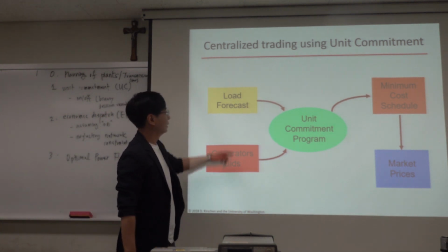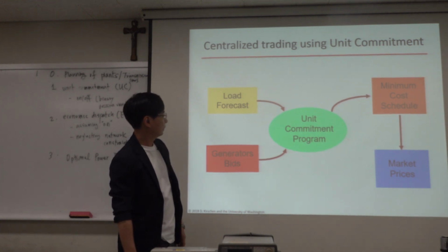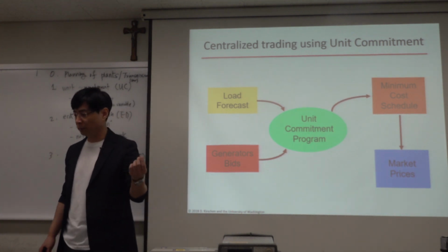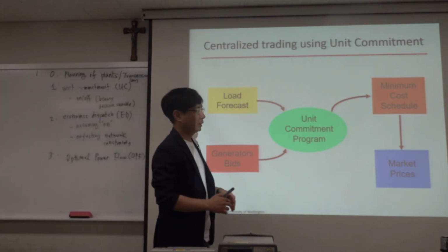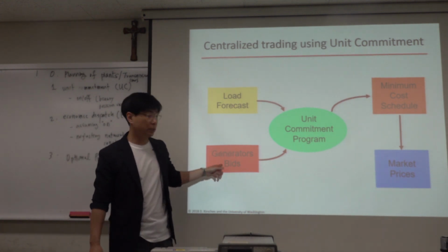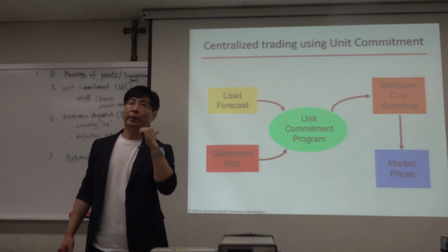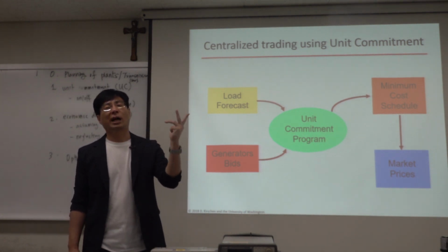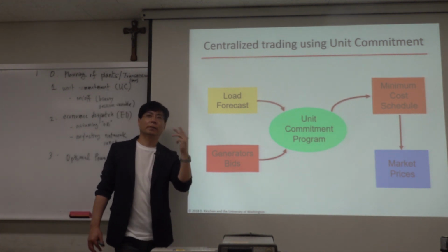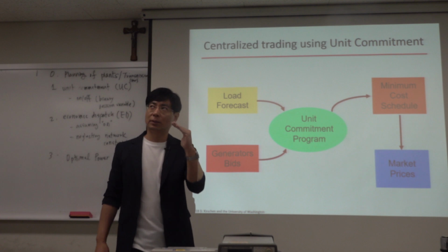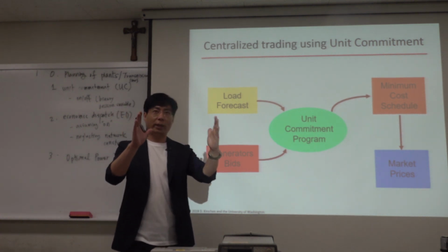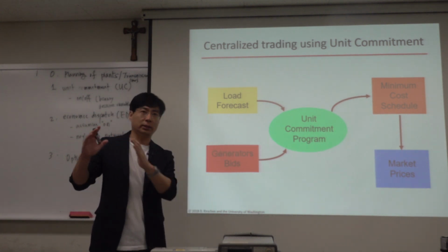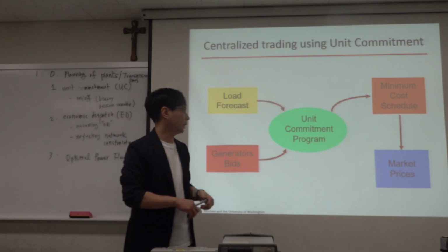In day ahead, they do load forecasting, and generators place their bids, and there are a lot of constraints about the generators: the minimum capacity, maximum capacity, the ramp up rate, and startup cost, and what else? The fixed cost and marginal cost. What else? Minimum duration when it is turned on, and the minimum resting period when it is off. Okay, so we have those constraints.